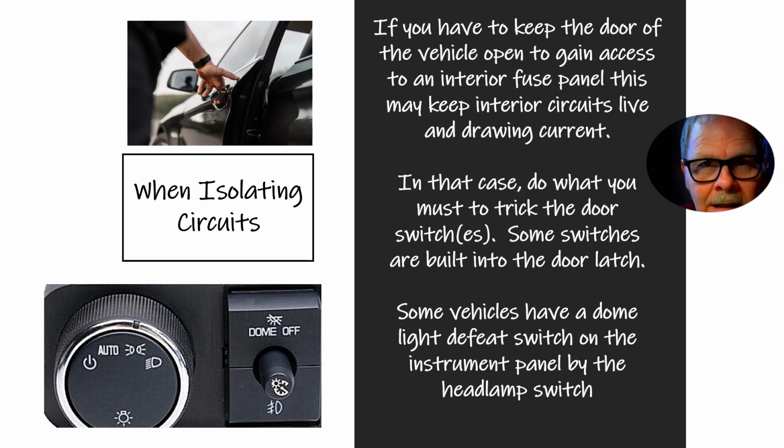Start with your main. If you look at a lot of these totally integrated power modules, won't have very many of your big fuses. Sometimes the power module itself will be a problem, but don't throw that on there first, because you may wind up spending money you don't need to spend.